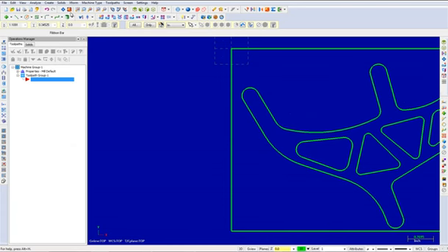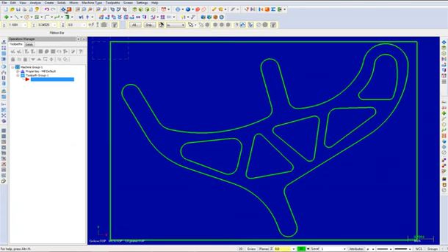Select the fit icon. To check the geometry, hold down the Shift key and select all of the chains as shown. Duplicate entities are identical entities. To remove them, you can use the Delete Duplicates command.